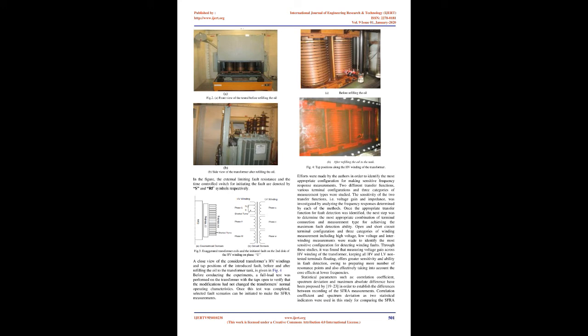In order to develop inter-turn short-circuit faults, in steps, the transformer oil was pumped out and the front wall of the transformer tank was removed to expose the windings. After the windings were allowed to dry, two conductors on the farthest layer of the second disc from the line end of the HV winding on phase U, located at two ends of the layer, were chosen and the insulation over them at a point on each was carefully removed to make tapping points.